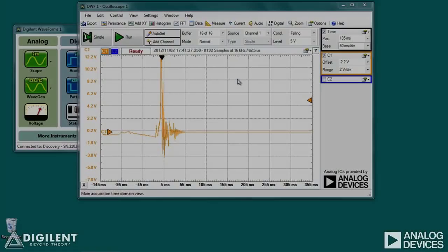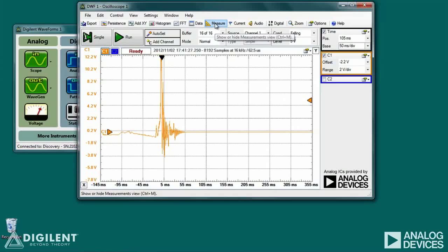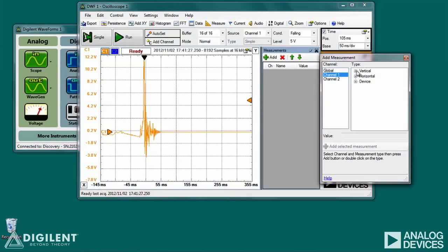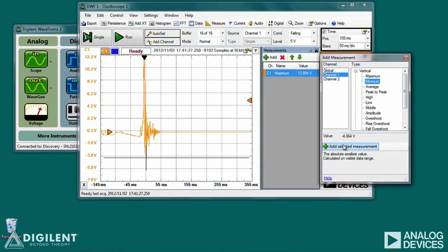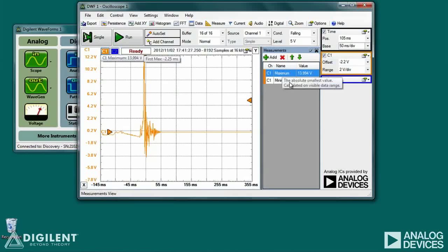Now we can use our oscilloscope to measure and display time-varying waveforms. We can determine parameters we want directly from the main window, of course, but sometimes it's a little bit tedious to make these measurements ourselves. There are a few tools available that can make our lives easier in this respect. Clicking on the Measure button opens a measurement window. This window displays a number of different measurement possibilities. You can choose the measurements you want to make. Those measurements will automatically be displayed in the measurement window.